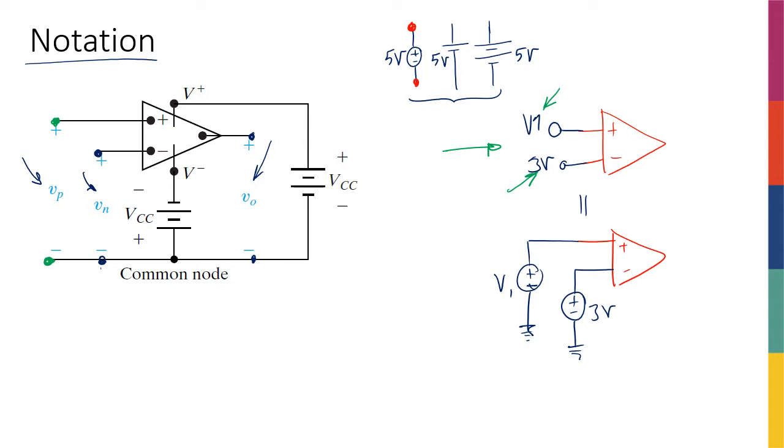Okay, so whenever I use a positive and negative and put just basically a parameter in between, I'm just trying to show the voltage across those two terminals, right? Those two nodes, this node and this node. Whenever I put a little circle, or it could be a filled one, or it could be a hollow one, right? It doesn't matter. If I show a terminal and just write one number beside that terminal, it means that that's the potential of that terminal with reference to that common node that we have decided. For example, here we have this common node, right?